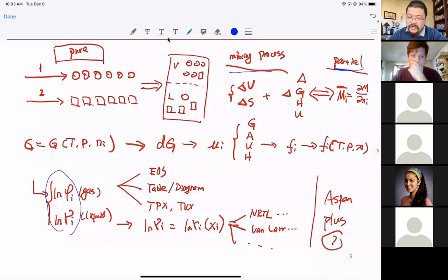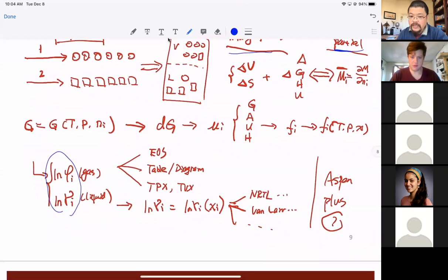One is specifically looking for the fugacity coefficient calculation. Right, we have TPX, TVX, equation of state, or using the table to run the calculations. On the other side, we are having the liquid, and we are looking at the activity coefficient. There we have lots of models, Margules, Van Laar, Wilson, NRTL, and so on, right? So those will be the discussions, and I hope that at some point, you realize that the reference and the standard state is still very critical.